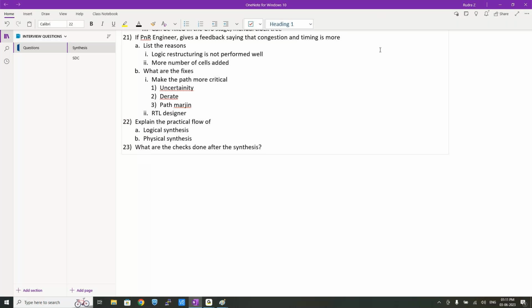Analyze and elaborate can be executed using a single command, the read verilog or read file command. You can perform it in a single step. Translation is also done to the tool understandable language.